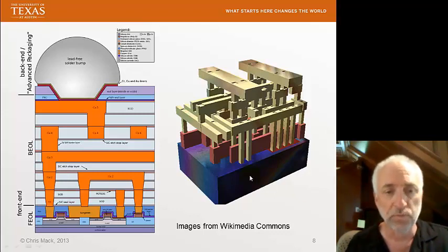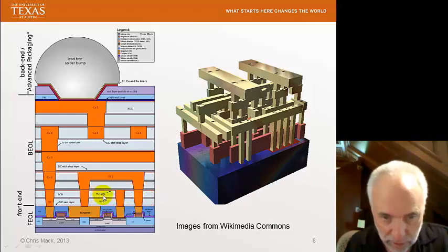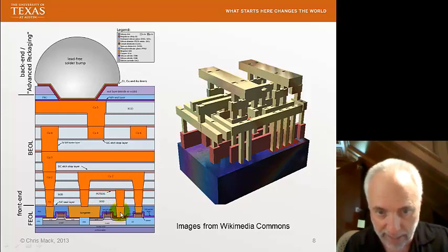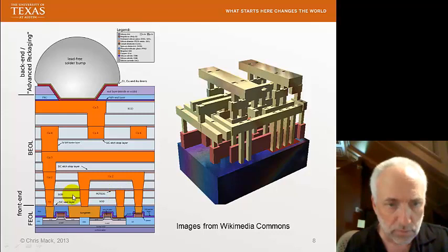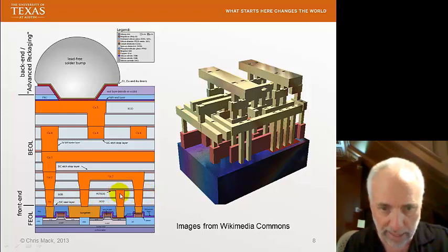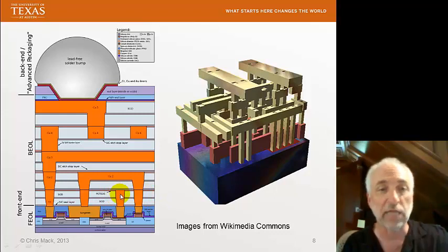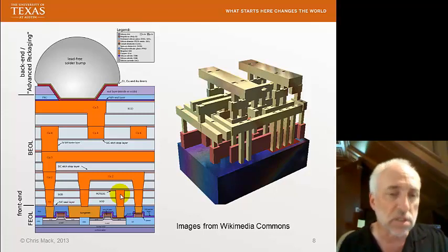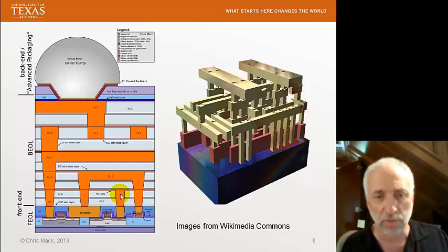So what do we have? We have a layer of metallization shown here, and then a contact from this layer down to the tungsten plugs through vias here. So in this case, the wires in this copper 1 metal, the metal 1 layer, are going in and out of the page. And we usually have all of our lines in one metal layer oriented pretty much in the same direction. That's the most common approach.